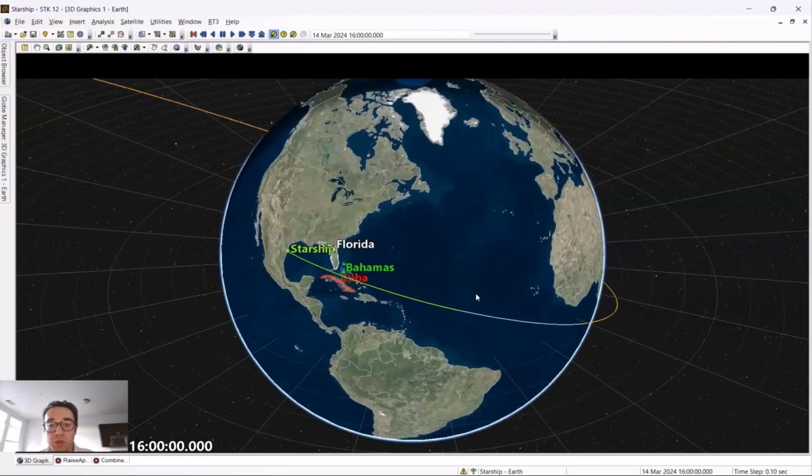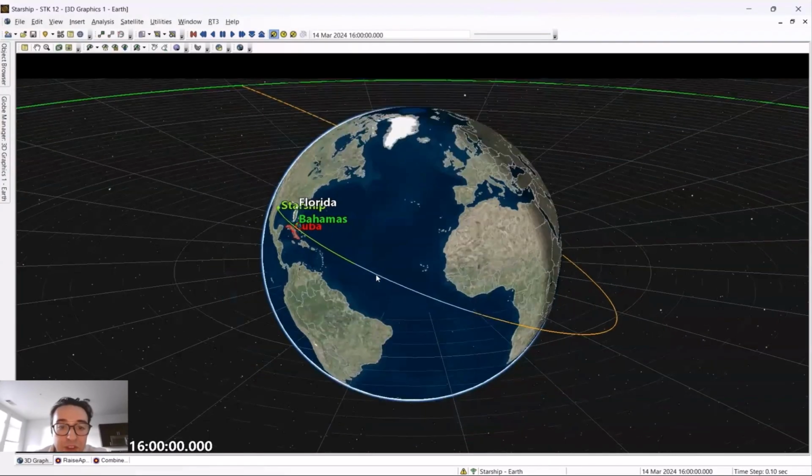So we managed to show these two things, and thanks to these parametric and carpet plot studies, we managed to also see which were the lower and upper bounds for our design variables, both the downrange distance and the azimuth at burnout. So we managed to see the optimum bounds for these two design variables, which allowed us to set up an optimizer tool run that was more efficient to start from because we had more defined bounds.